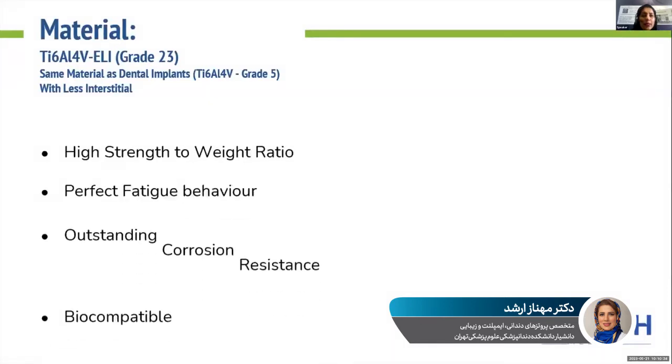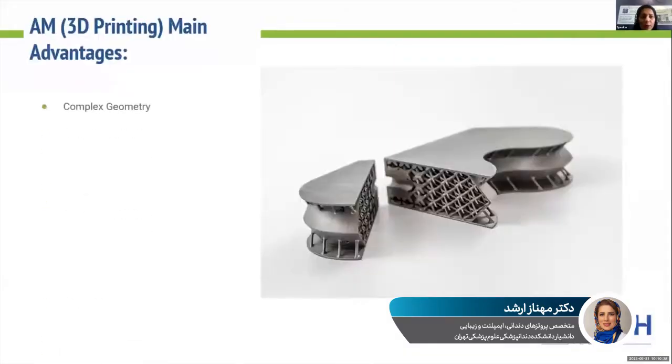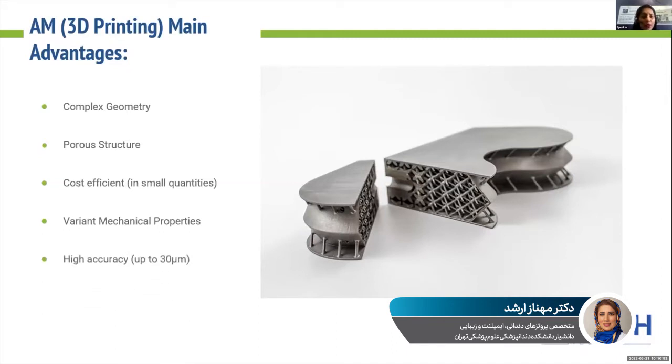The material is titanium grade 23, and it has a high strength to weight ratio, perfect fatigue behavior, outstanding corrosion resistance, and is biocompatible. It must have complex geometry, porous structure, be cost efficient in small quantities, have variable mechanical properties and high accuracy, up to 13 micrometers.